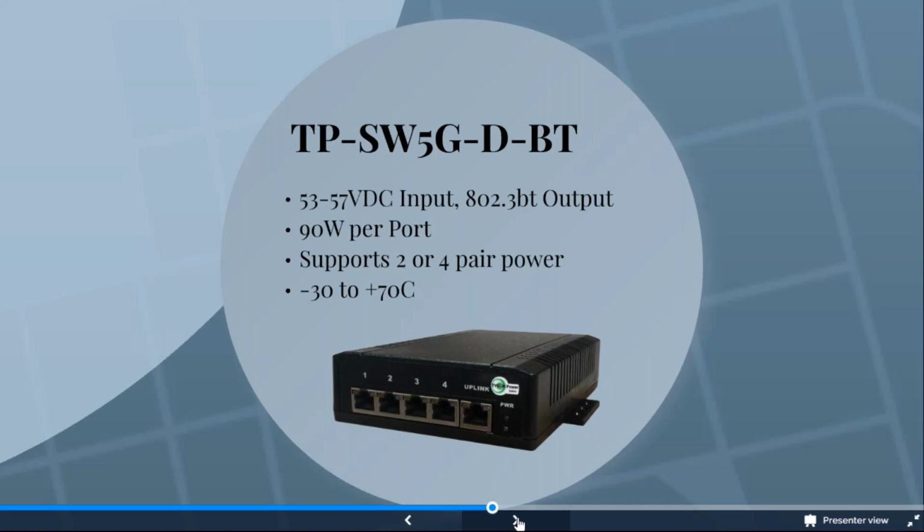So just because it basically says it's, you know, capable of 30 watts, but it's only going to send you 15 if that's what your device requires. So you don't need to worry about providing too much wattage. Voltage is where we really have to be concerned, is that we need to make sure that we're providing the right voltage for that. So even if you are powering some AT and BT devices, this switch would work for you, just knowing that you're having up to that 90 watts per port option.